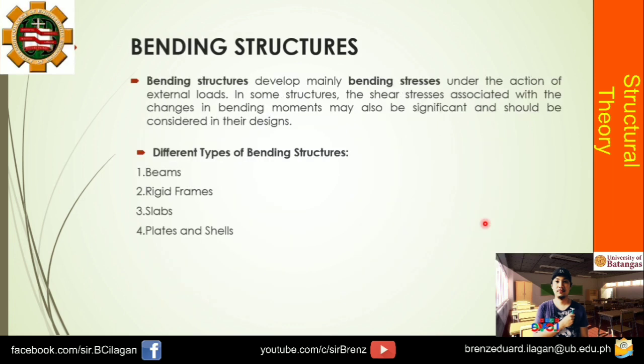Okay, for bending structures: beams, slabs, plates, and rigid frames. So, bending structures develop mainly bending stress or flexural stress under the action of external loads. In some structures, the shear stresses associated with changes in bending moments may also be significant and should be considered in their design.